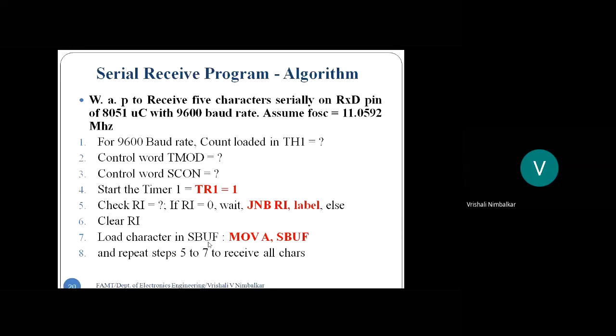Are you getting me, students? So one by one, as the bits arrive, they are not directly kept in SBUF. They are kept in an internal temporary shift register. And when the shift register receives all the 8 bits, the microcontroller picks up the data from the shift register and loads it in SBUF. And the user can only access SBUF.